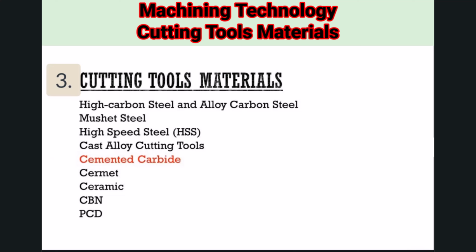In comparison to high-speed steel HSS tools, carbide tools are more wear and heat resistant, and you can have higher RPM, cutting speed, and feed, allowing you to machine your parts faster and save money. However, carbide tools are more brittle compared to HSS tools. Therefore, you need better spindles and fixtures. Generally, HSS tools are mainly used in manual machines, while carbide tools are used in CNC machines.